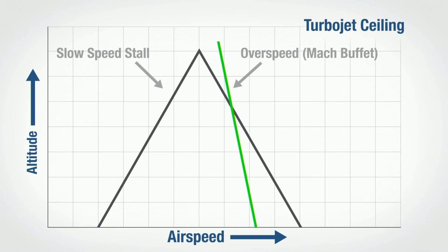In the past, older aircraft essentially were capable of flying faster than their critical Mach number. And so this green line here you could look at as the aircraft's maximum speed. Okay, so at sea level, the airplane doesn't generate enough thrust to get faster than the speed of sound. Okay, but at some point in time, it does have enough thrust on it to get faster, maybe not than the speed of sound, but faster than its overspeed number, its critical Mach number.